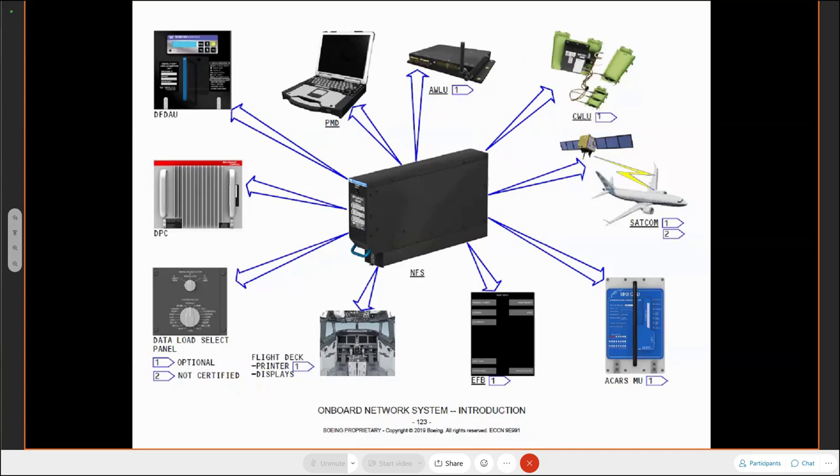At that point, it depends on who's controlling the software, the individual airlines, but the system will search for software updates, and any applicable software updates will automatically be downloaded from the servers, things like Software Librarian, which the enabling team organise. That software will then be downloaded to the network file server and stored on the hard drives, or you may see them referred to as mass storage device. That is just a hard drive.